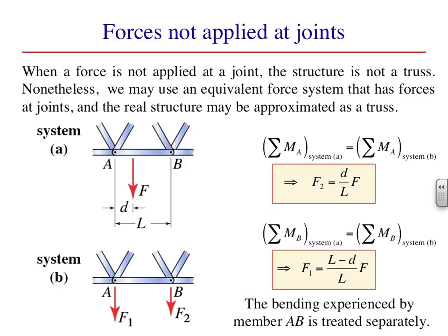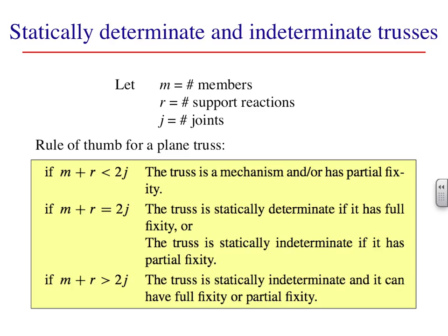It is usually the case that our equivalent force systems principles apply only in the case of rigid bodies. Real structures are extremely stiff along their long axes, however, so they still appear to be rigid even though they are made of deformable material. As our truss analysis involves only axial loads, we can get away with the use of an equivalent force system principle in this case. The next couple of slides address the issue of static determinacy.